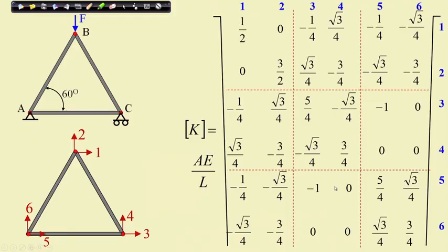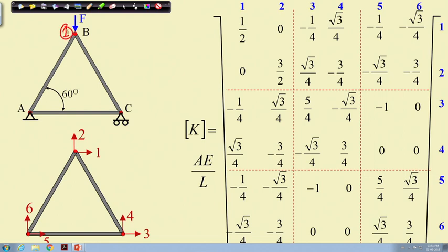Okay. If you recall, this was the problem that we are trying to solve. This was the truss, and we have different node numbers, say node number 1, node number 2, joint number 3, and the corresponding member numbers. Once we have these, we determine all the stiffness matrices, then assemble them, and get the global stiffness matrix. These 1, 2, 3, 4, 5, 6 are associated with degrees of freedom. At each joint, we have 2 degrees of freedom. So, total 6 degrees of freedom, and the size of the global stiffness matrix is 6 by 6.